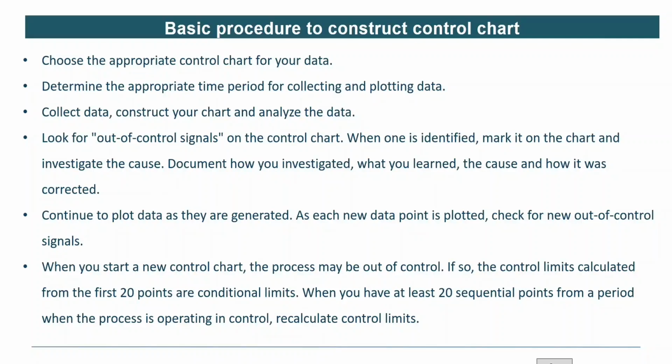And once you are clear on this, once you have constructed this control chart, then you need to start plotting your data at the agreed frequency. The frequency can also be decided by your process expert because the frequency changes from process to process, but it is with respect to time. So you collect data with respect to time and start plotting the data with respect to time. And once you start plotting the data with respect to time, you will be able to identify statistical process abnormalities.